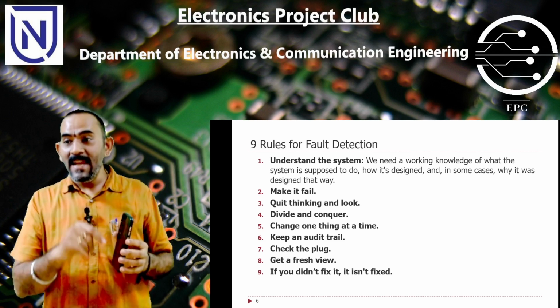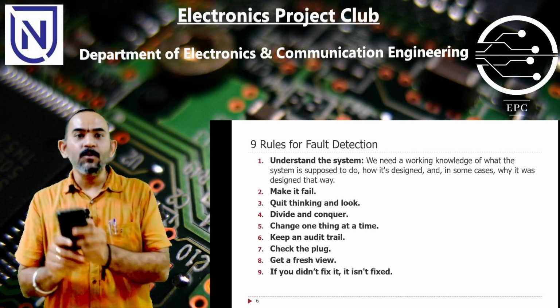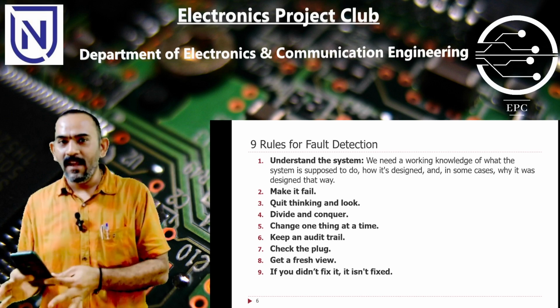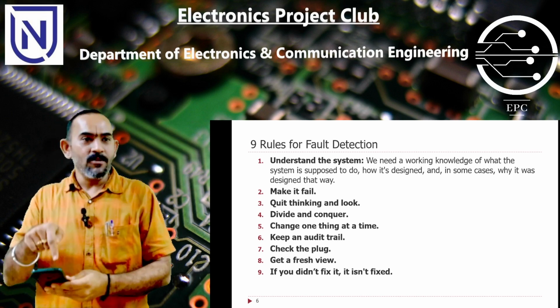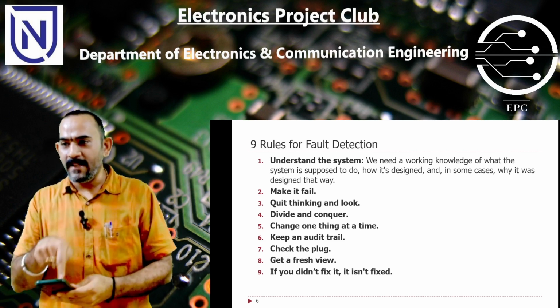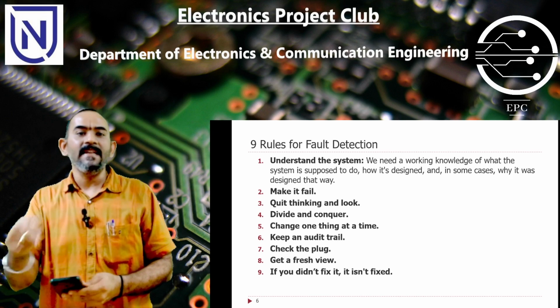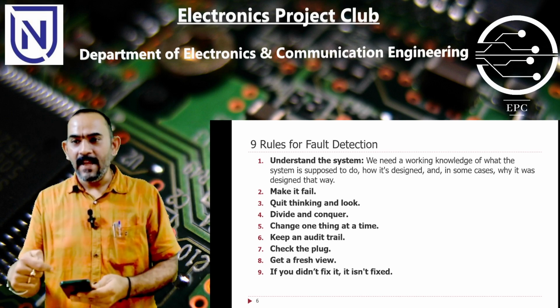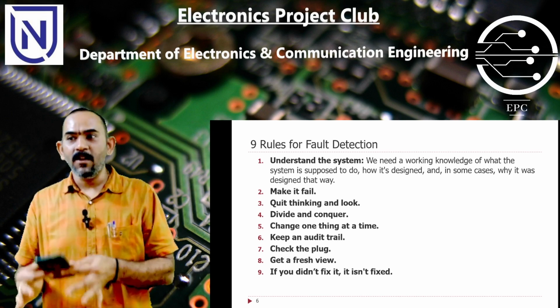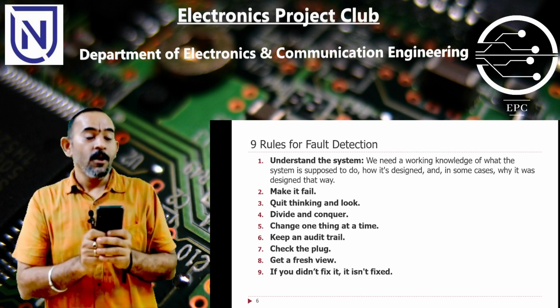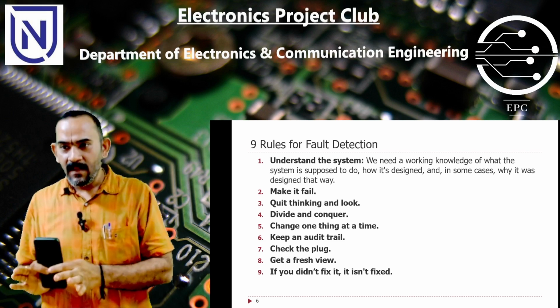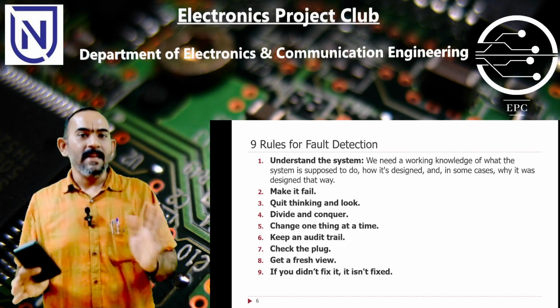So now to really test this condition, first thing is you have a test board with you on which you are testing. The customer is somewhere else, so you need to be able to reproduce the same failure on your test board. Then only you can debug why that happened. And the board you have may not be the same board as what the customer is telling in the complaint. So unless you make this fail, you can't really debug it.